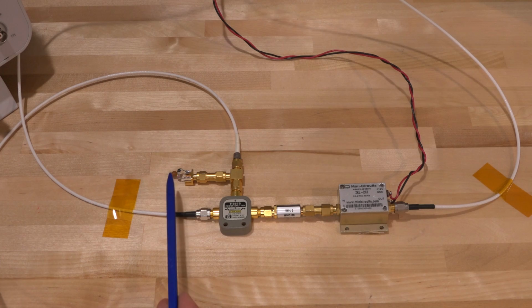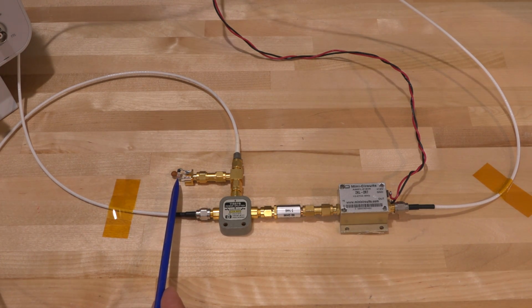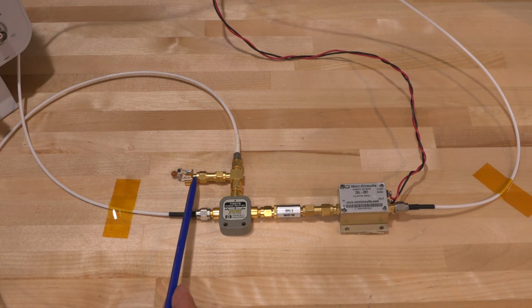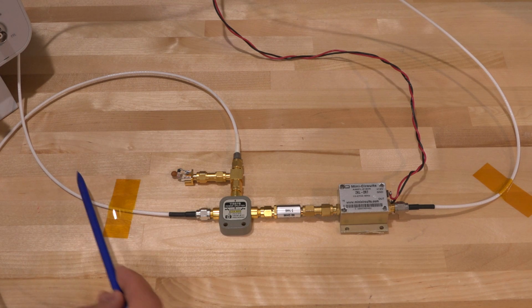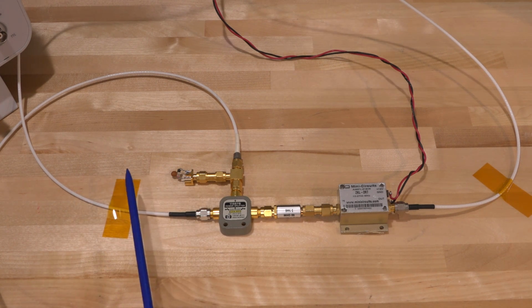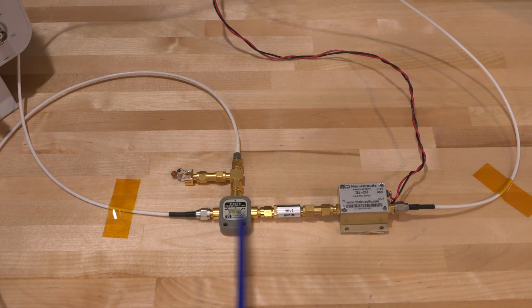So not only do we have a capacitive component whose impedance changes with frequency, we also have a diode whose impedance changes with signal amplitude. So we have a very problematic input here, because depending on the signal amplitude and frequency, the shape of the waveform at this point will change, because it's directly loading the output of the function generator, which is 50 ohms. After that, we go into a 50 ohm power splitter,